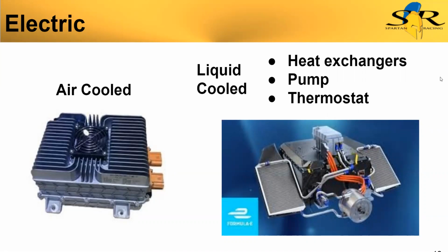Yeah, so there's a few different ways. I think a more common one is that each of these separate systems will have its own cooling system with its own pump and its own heat exchanger or radiator. Another way to do it is just to run a bigger pump that can handle the flow and all the restrictions.